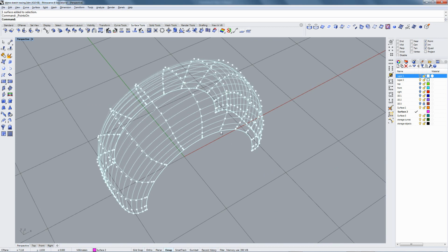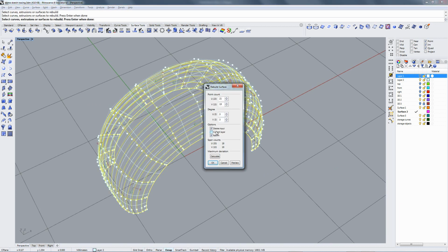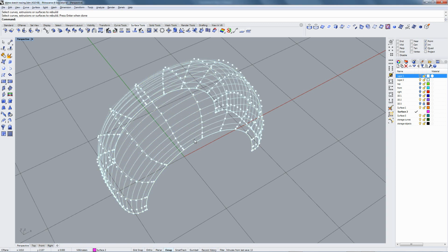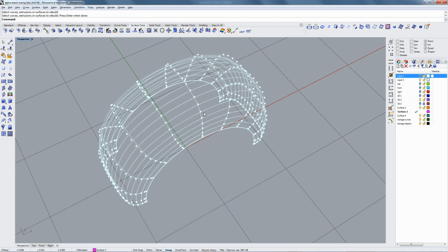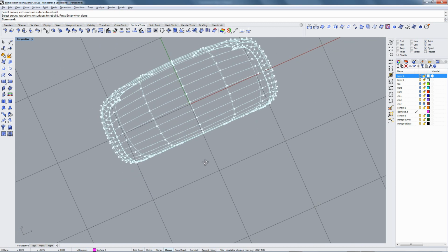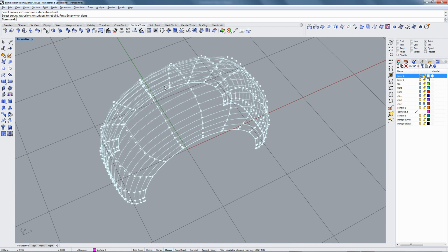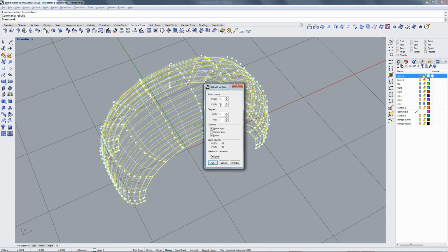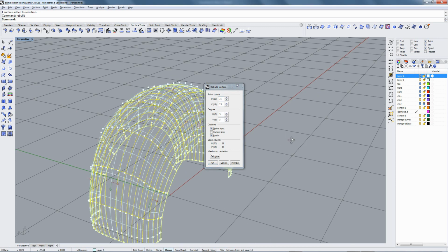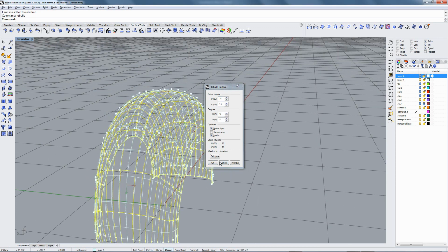I am going to take a look and see what the surface is right now. It's 23 versus 13. I do want to keep the 13 because it's going to give me a control point seam along the midline, which is really helpful for symmetrical work. The really dense 23, that's a lot to cover that kind of curvature, but it's all right. I'll keep it.